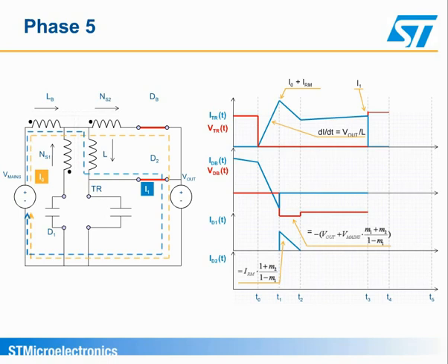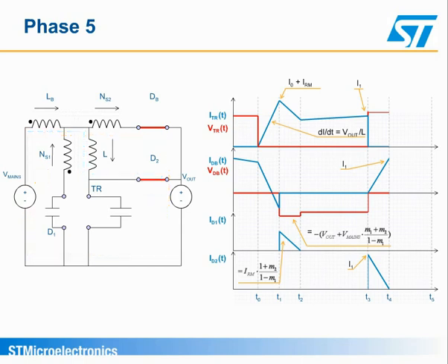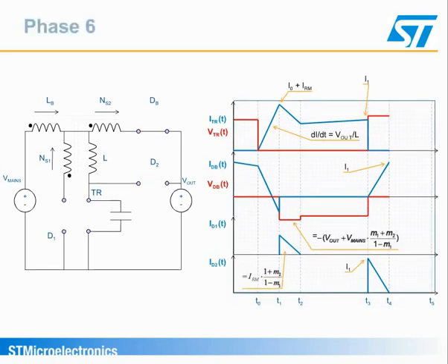The auxiliary windings, NS2, then act as a negative voltage source applied across the inductor L and cancel the current I1 through it. Consequently, starting at I1, the current in diode D2 decreases down to 0 amps, while the current in the boost diode, dB, increases to reach the nominal current at T4. At low line, the BC squared gives a significant advantage due to this current sharing through the two diodes, as the conduction losses are reduced. Finally, the BC squared goes back to a normal operating mode.